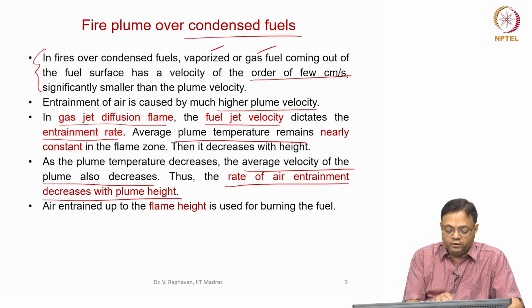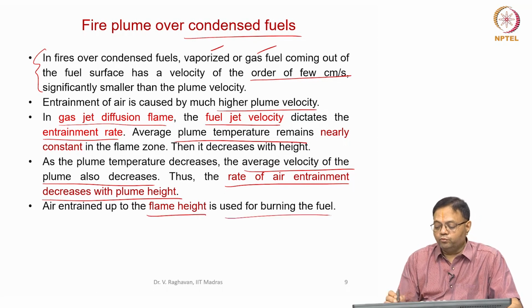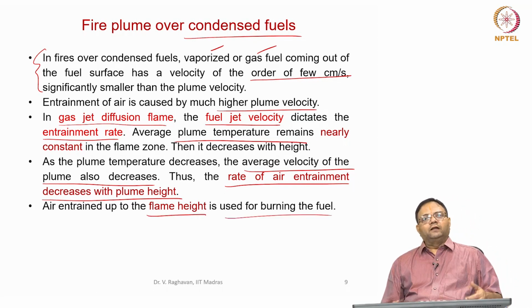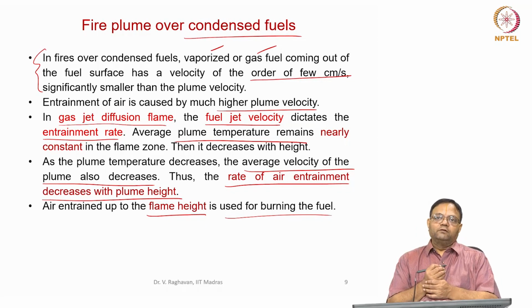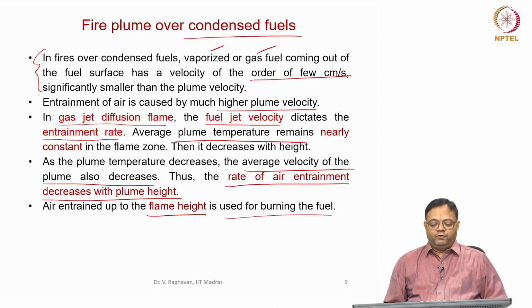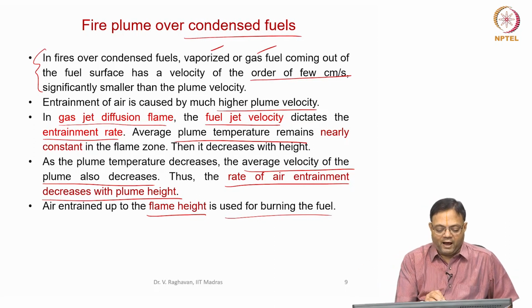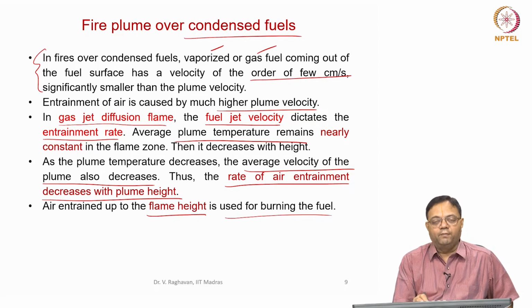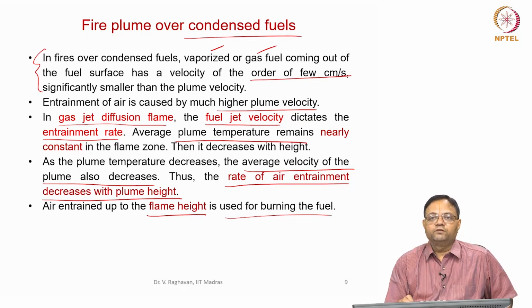So, now the air entrained up to the flame height is used to burn the fuel basically, and that is more than enough to burn the fuel in several cases. Okay, now in a compartment etc., it may not be true, but in open flames we can say that the air entrained up to the flame height itself is sufficient for burning the fuel.